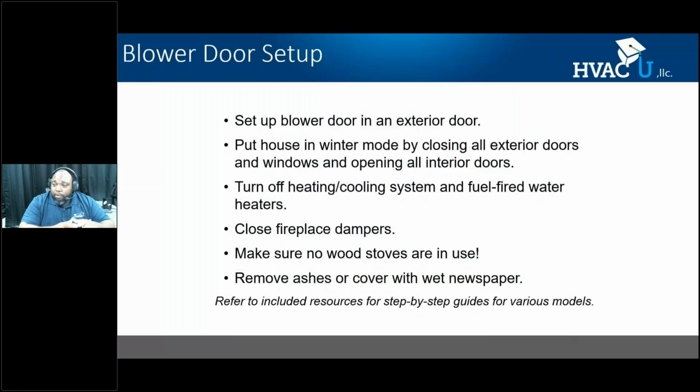When we set up a blower door, we're going to put it in any exterior door. We're going to put the house in wintertime conditions. Basically, that means all the interior doors are going to be open, all the exterior doors are going to be closed, and all the windows are going to be closed. We put that fan in one exterior door that we plan to use. We're going to turn off all our combustion equipment, disabling our water heaters and our heating and cooling systems.